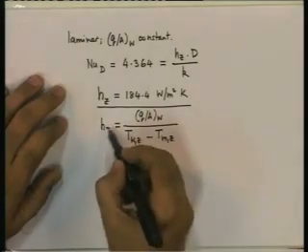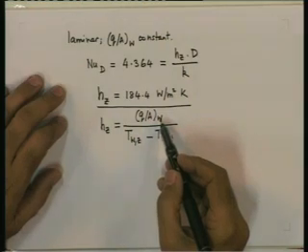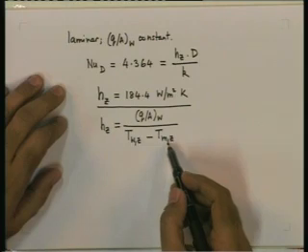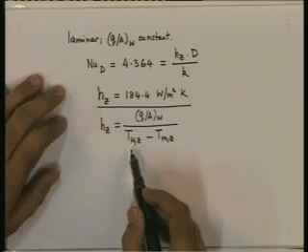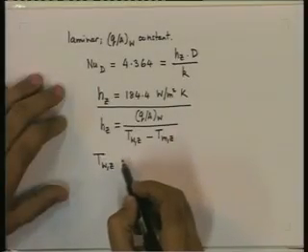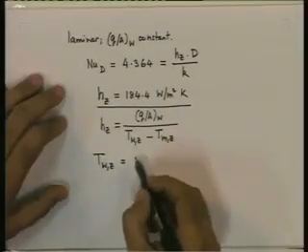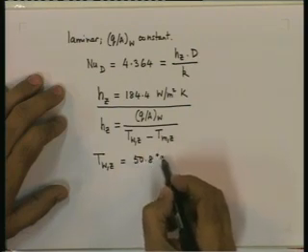So we know the heat transfer coefficient. The wall heat flux is specified 2000 watt per meter squared. Tmz is specified 40 degrees C. So the only unknown in this equation is Twz, and if you calculate that out, it turns out to be 50.8 degrees C.